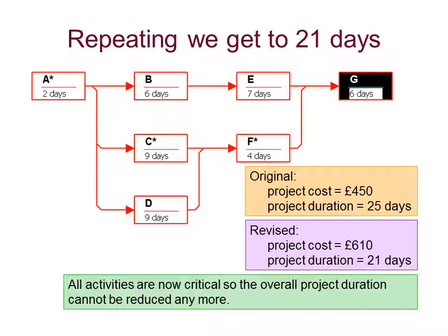Okay. The other important critical point is that in crashing the project, we have reduced the duration of the project down to 21 days, but in so doing, what have we done? We've increased the amount of critical activities in the project. There's no float left, all activities are critical, and therefore we've increased, commensurately, risk. If something goes wrong in any of those activities that formerly did have float and therefore contingency, we have no flex in the project to allow for those sort of problems.